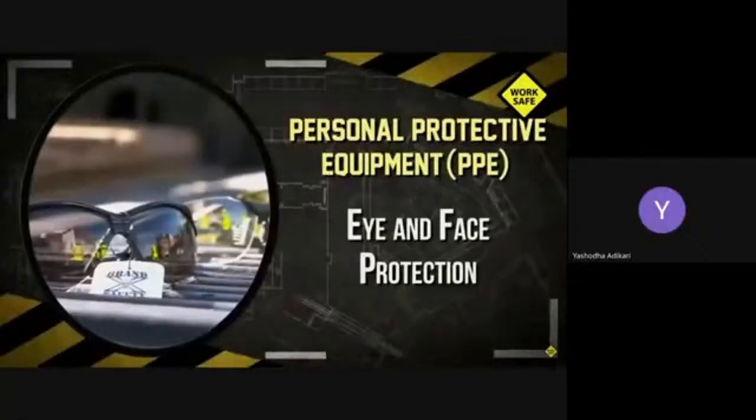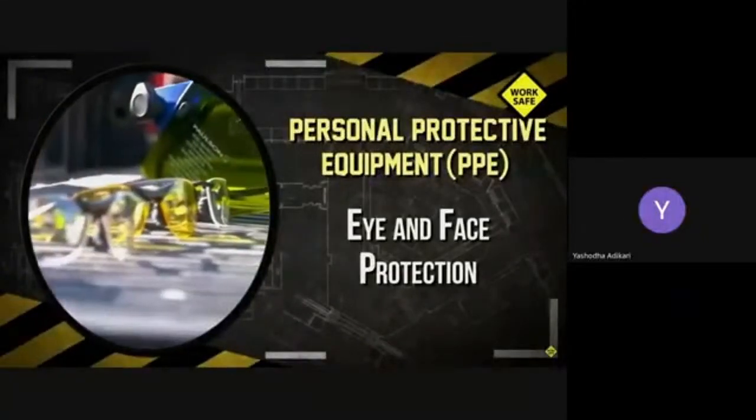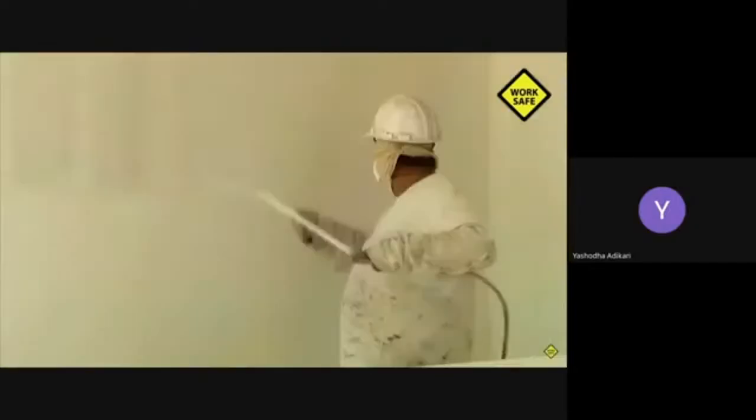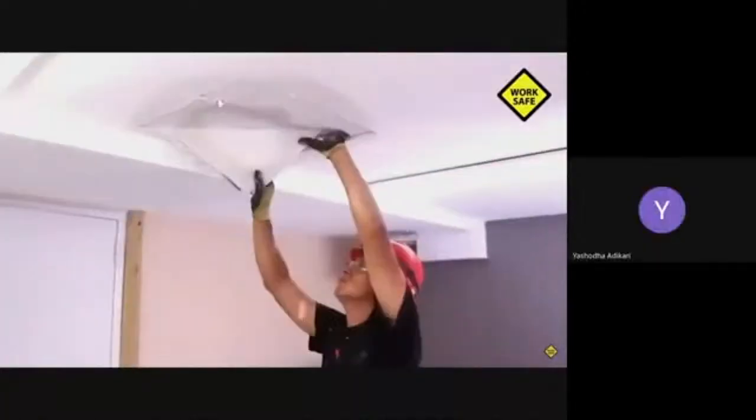Eye protection and face protection should be chosen based on what tasks are being performed, such as impact from flying objects, chemical splashes, harmful dust, or radiation from welding. You must wear impact-resistant safety glasses anytime you could be exposed to flying material, even if you are not working directly with that material. All eye and face protection must meet ANSI standard Z87.1.